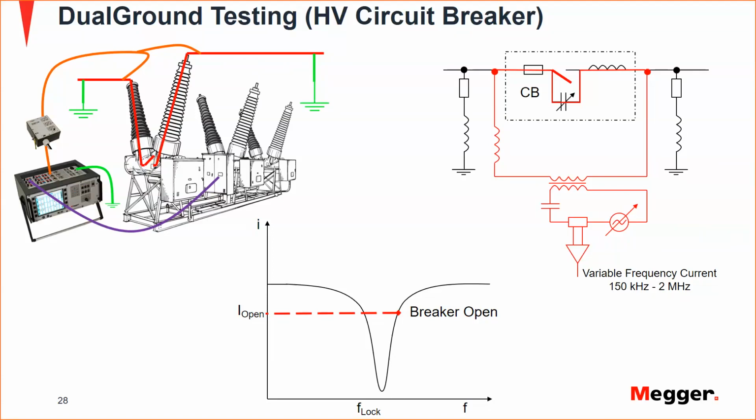The method we are using is called DCM, dynamic capacitance measurement. Basically, whenever the circuit changes, either open or close, that's seen by this DCM method. We will be able to detect open or close status very, very accurately.